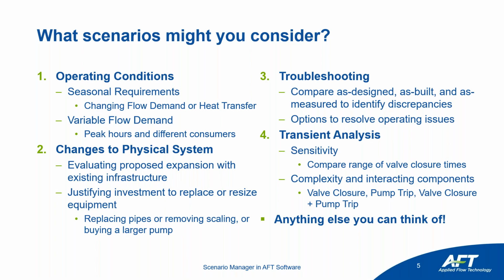Something I do as a support engineer is if someone is sending in a model for me to troubleshoot, usually I'll create a child scenario immediately. I can reassure myself that I can make any changes to that scenario I want, and it won't impact that base scenario or all of the hard work in the original model that they sent in. I'm able to preserve that while still having the flexibility to make tweaks, experiment, pull on strings that I want to pull on to try to identify the issue within a model.